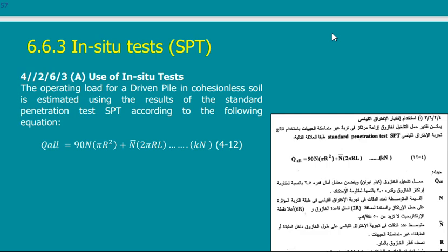It means that if you use different equations, you will get a variety of values. So which value is the correct one? I really don't know. How can I judge which is the correct one? I have to perform a full-scale pile load test on site prior to construction, because I may change my design based on this.